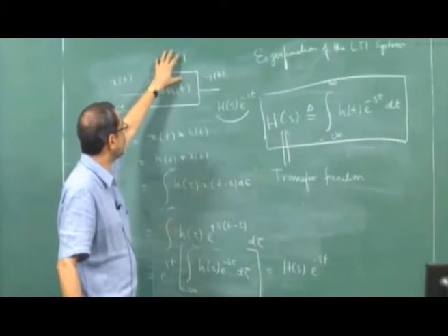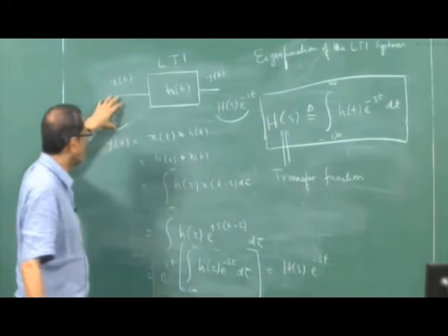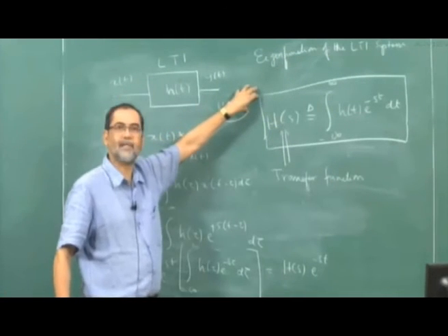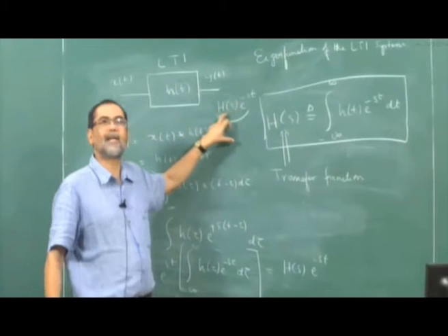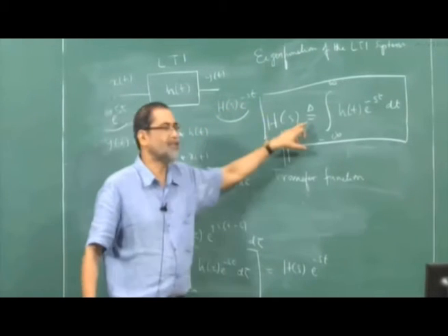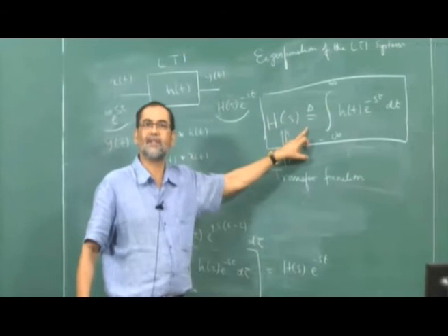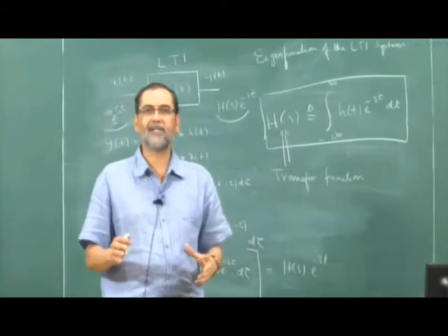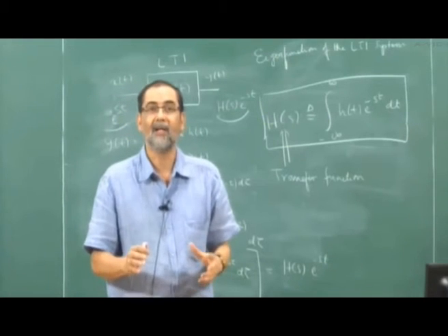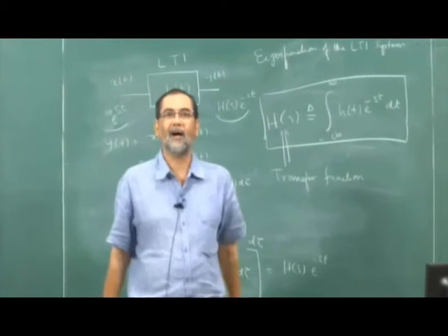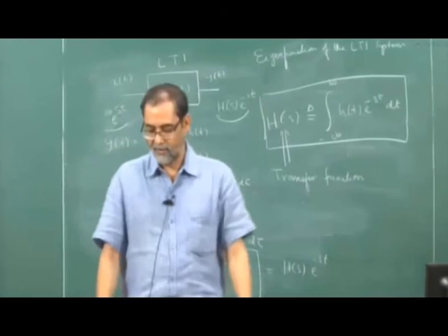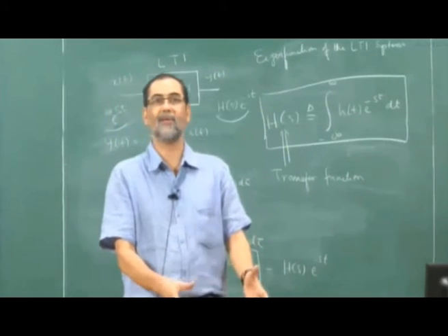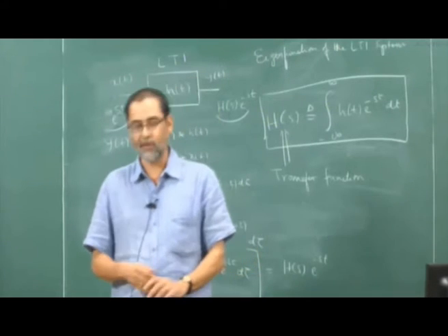For an LTI system with input e raised to minus st, the output is the same frequency e raised to minus st with some scaling factor H of s called the transfer function, defined by this integral. So this idea that linear time invariant systems preserve the frequency leads to the study of linear systems in the frequency domain. That's what I'm going to do next. So that's the motivation for switching to the frequency domain.